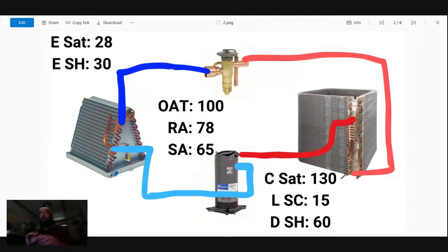And yes, I would have concerns if it starts to function the way I wanted it to after I adjusted it, but it's been an existing system with no other dramatic events, like they haven't had compressors or anything dramatic happen. What's going on now? Why did that valve stick internally? Because that's what it would tell me, that something stuck. If it worked like it was supposed to for all these years and now all of a sudden this happens, something happened. It doesn't mean the valve needs replaced, but we need to start asking more questions, and those are the right questions to ask.